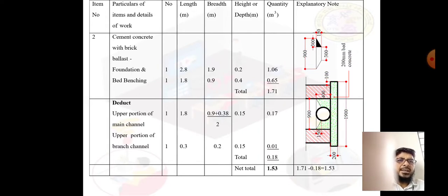It is cut exactly at the center point of the pipe, meaning the sewer is cut 50%, and the benching is tapered. The total width of the tank is 900 mm, and it is joined at the mid portion, the center of the sewer. For width, we can take the diameter of the pipe. So the inside diameter is 0.38, and the outside diameter is 0.4 meter. So the inside point will join, okay.